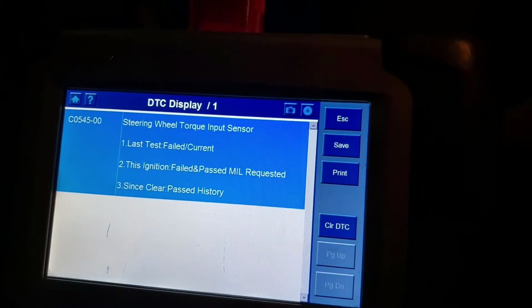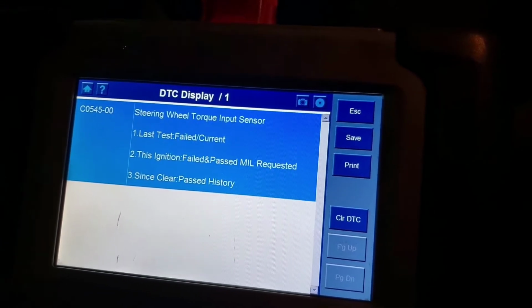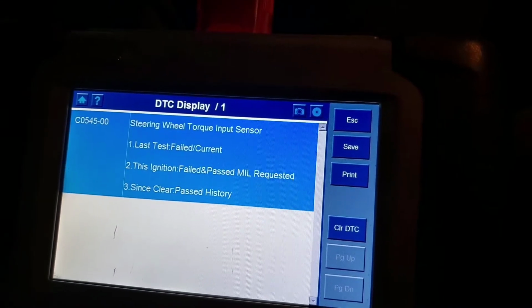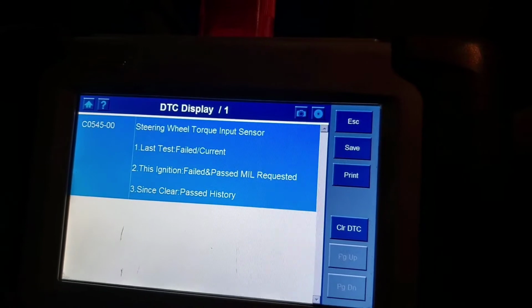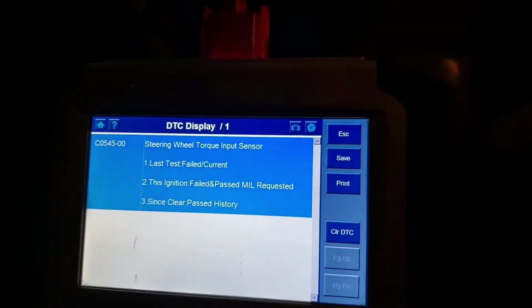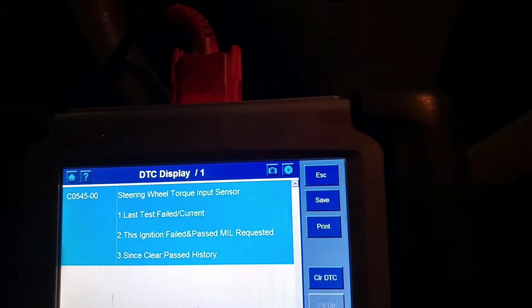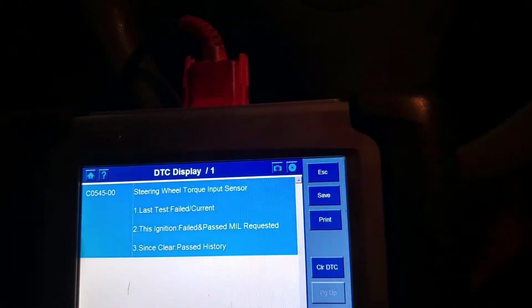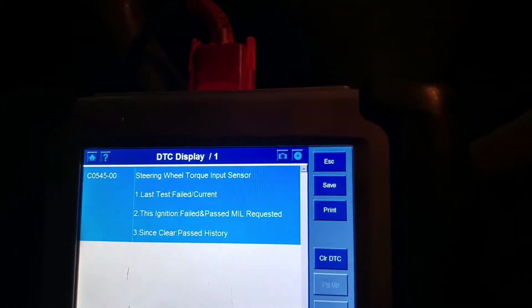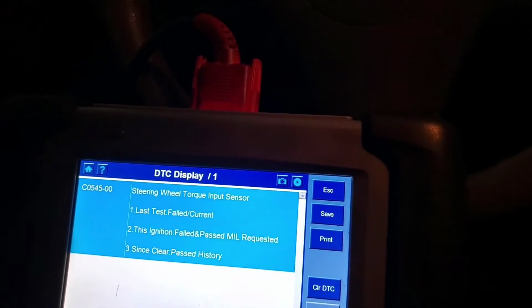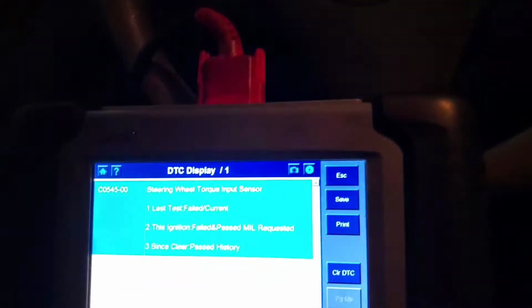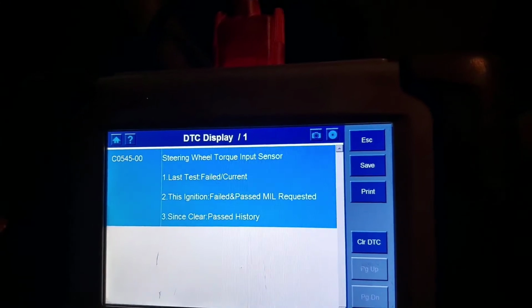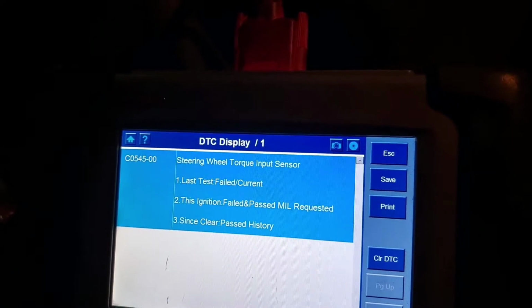On some manufacturers, I guess if this is electric power steering, I'm going to assume it is, I haven't looked. But on some manufacturers, the assist motor, the electric motor, is on the column. On some, it's on the rack. On some, it's a hydraulic system whose pump is electric. So I got to look and see which system I'm dealing with here.